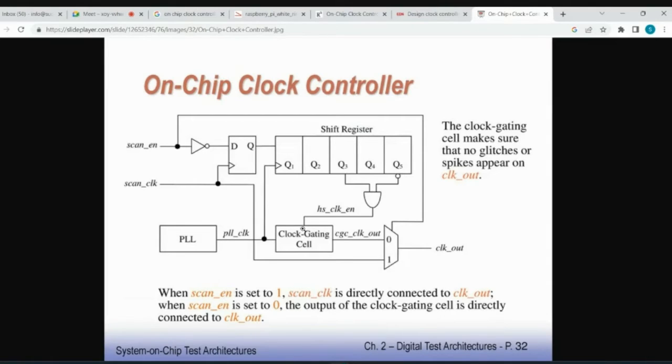So we have to learn what a clock gater is also in this process of learning OCC. We will learn it. For now, let's try to digest this concept where your scan clock or the reference clock is going to the PLL, and that is also a separate path, a free path. The reference clock is directly going as input to this particular mux.